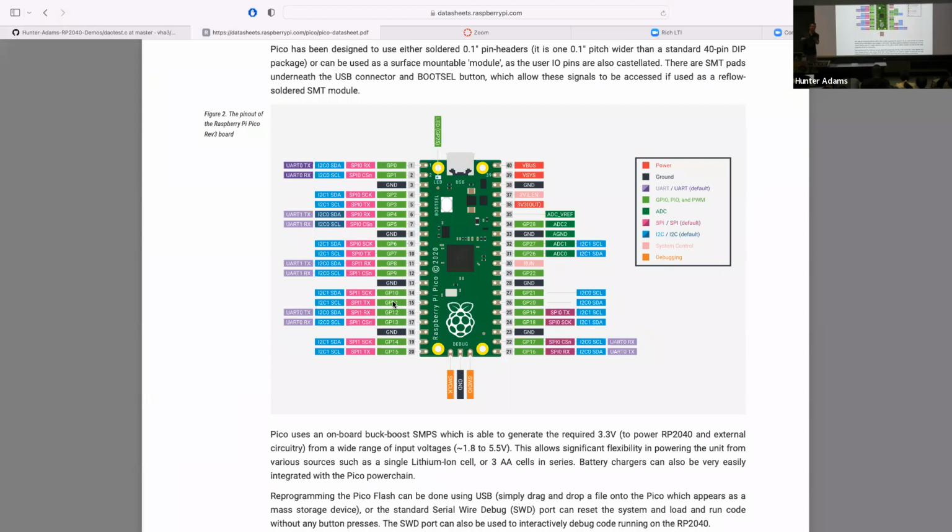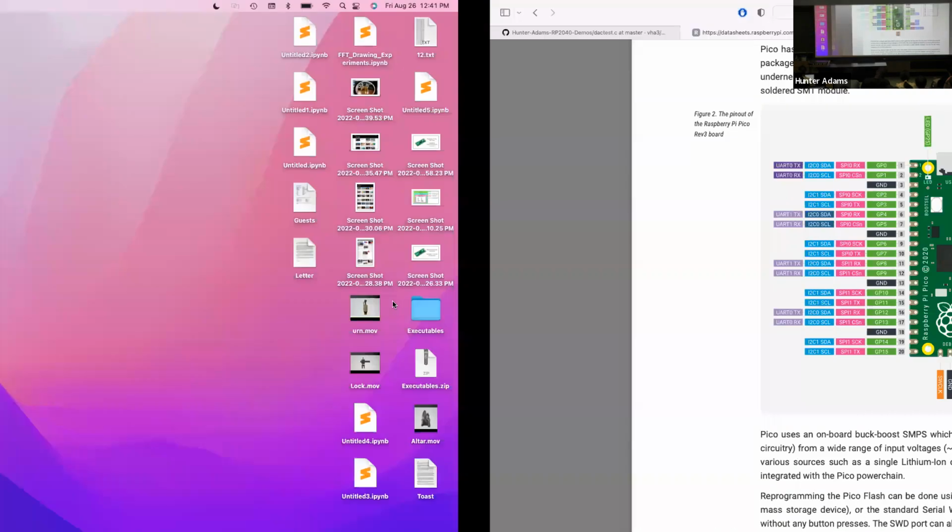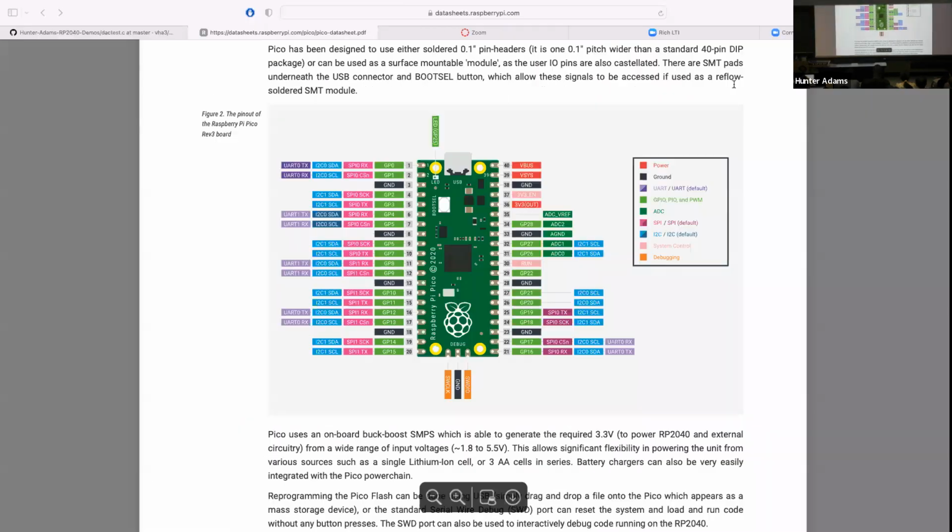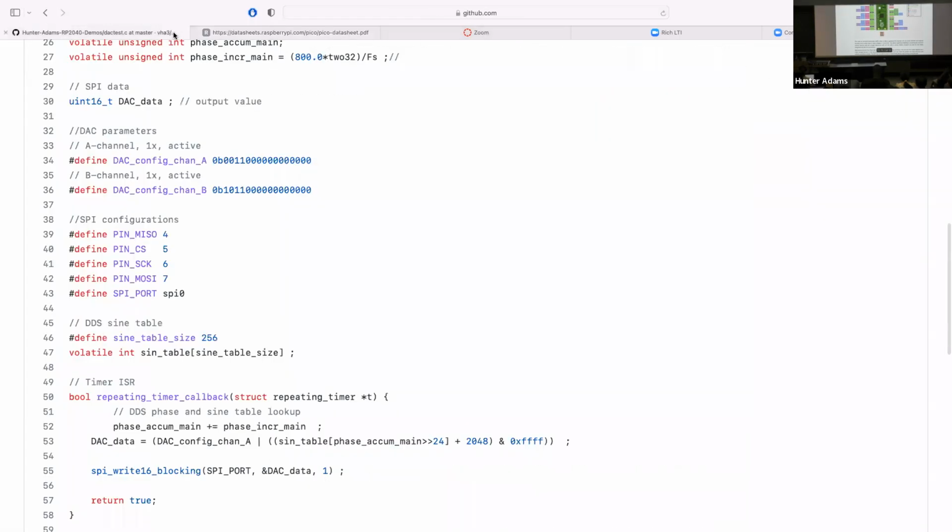And by the way, an easy mistake to make, I've seen this mistake in lab a couple of times. Just remember that the GPIO number is different from the physical pin number. Right, so for instance, GPIO 5 is attached to physical pin number 7. So when you're wiring things up, just be cautious of that. So that, in any case, that's where those GPIO values come from.